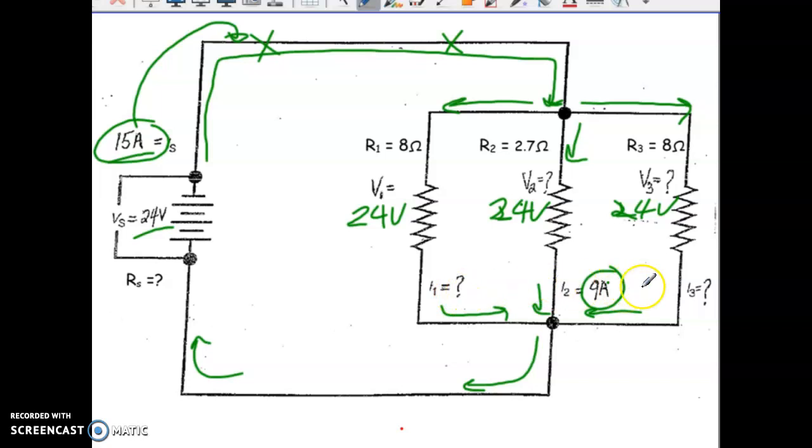Now you cannot really make an assumption that these two are going to be the same number. However, in this particular case, you actually can. The reason why is because you can use Ohm's law to solve for the missing information. Because I have R and V, I could solve for I that way. V is equal to I times R. So I would be equal to V over R. So we actually could solve for this using Ohm's law.